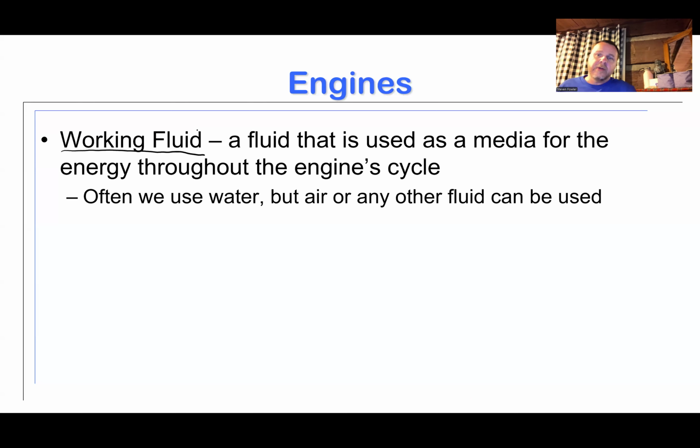There are two main working fluids that we'll consider in this course, with water being one of them. Water has a very high specific heat content. It's fairly easy to obtain, fairly non-corrosive, but the biggest thing is it will take a whole bunch of energy before it increases in temperature. And it takes a whole bunch of energy to get it to vaporize. It's a really good way of storing a lot of energy in a way that's pretty safe to work with. And again, it's not toxic. It's just easy to move around and it's reasonably easy to acquire.